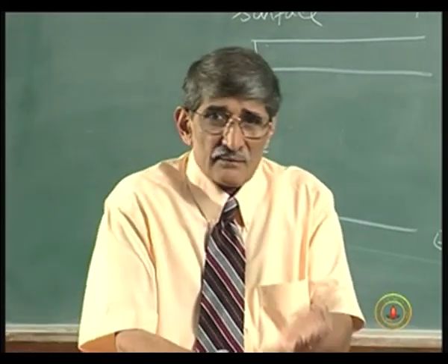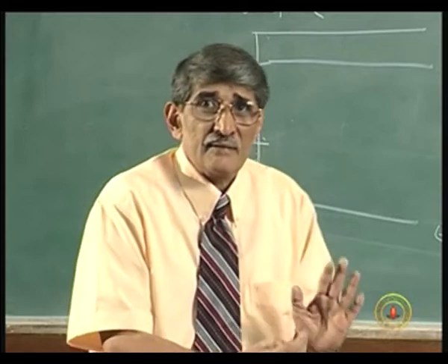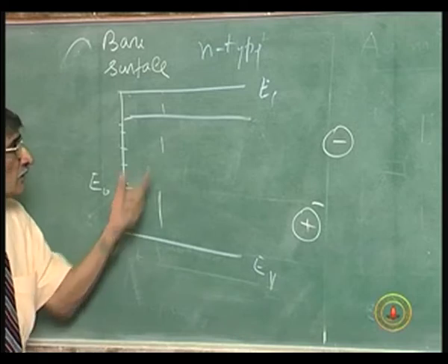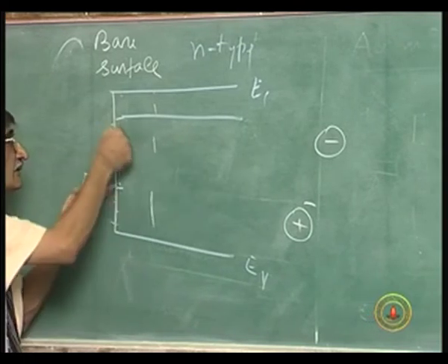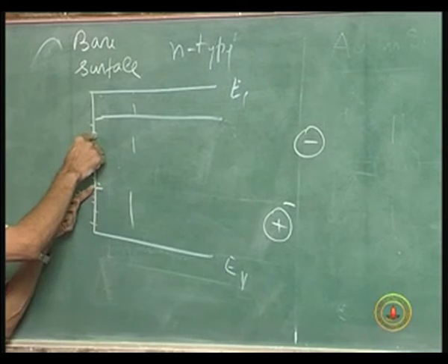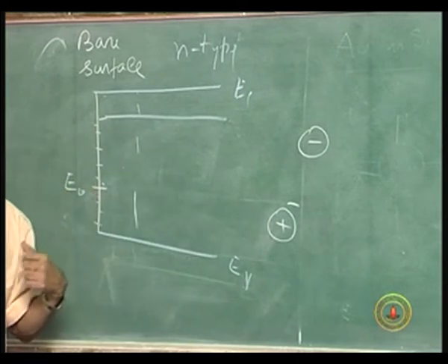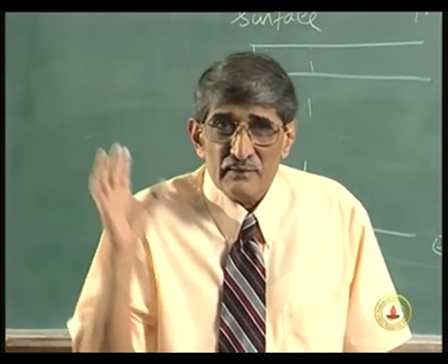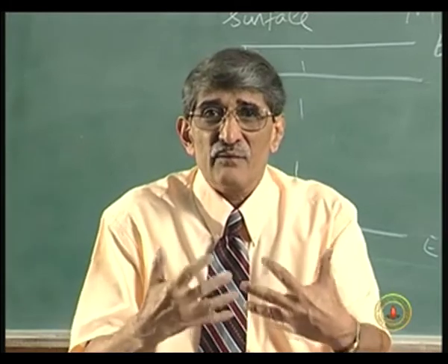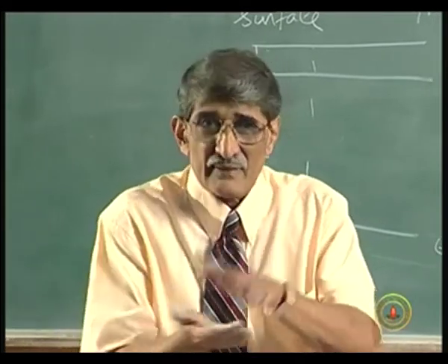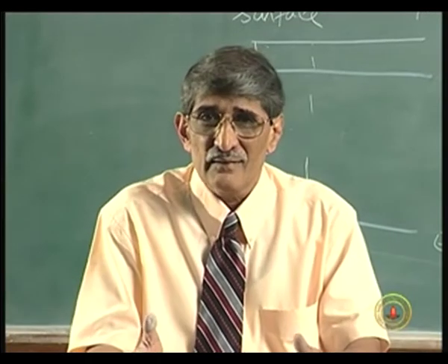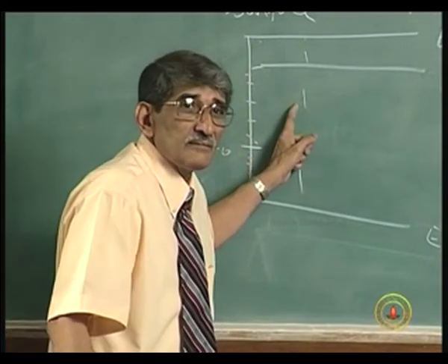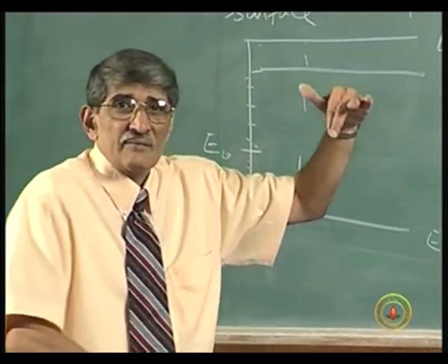In the N-type semiconductor, electrons have been removed from some region. So, this region has contributed the electrons here. That means this region will be depleted. I think I will discuss this next lecture, because this is a very important concept. What emerges from here is, even if you take a free semiconductor surface, do not put any metal, it will have a depleted surface, because these electrons have to be supplied from this region. So, the entire energy band diagram will bend.